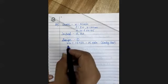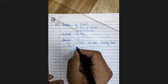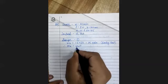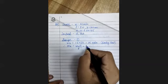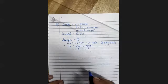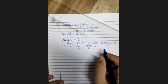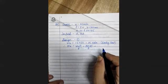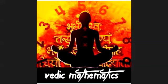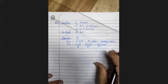So limiting load we got. So now can you find out Mu? So find Mu now. Mu is Wu L square by 8. Okay, Wu is 75. So this is how much? 600. Yeah, so this is your ultimate moment. Okay, so now for this moment we have to design the section.